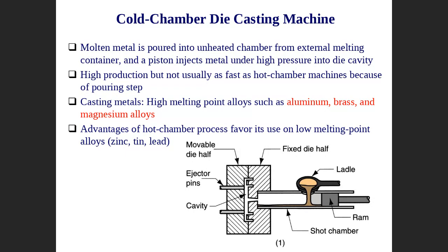Yes, it is liquid metal because this one is very hot actually. This area is very hot. Even though we call it cold chamber, it is very hot. And then when you push it, it happens in a fraction of a second, very fast. It's not that long a time. Solidification takes longer time, right? So it happens in a fraction of time, so this one is still remaining liquid. When this one releases and you put liquid again, all will be liquid here, and then the process will happen in a very short time actually.